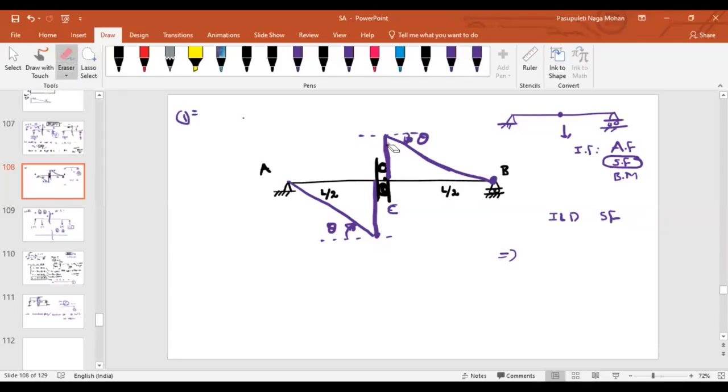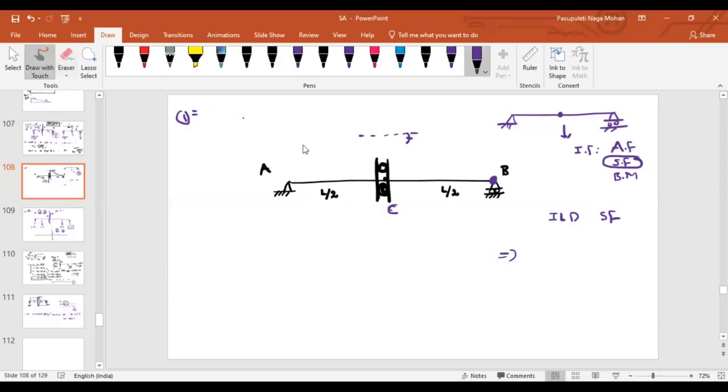So that's why in this case, I have just placed the vertical shear hinge. That means if I take a support like this in between, if I take this type of arrangement, only at this section the beams can move along the vertical direction. At the same time, it will not release the axial force. At the same time, it will not release the bending moment.